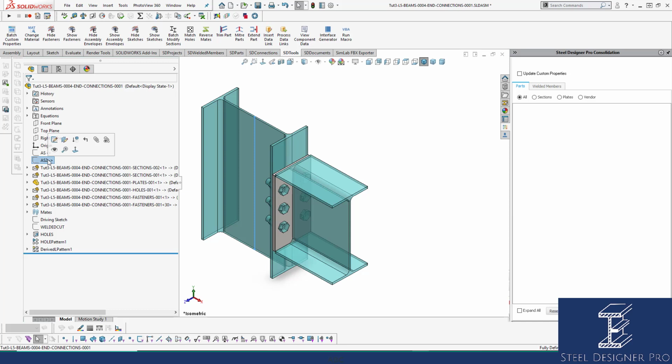and this is where we talked about driving sketches and maintaining a direction, which we keep as a consistent direction of sketching. So when we insert this connection, those attachment sketch segments are related to the driving sketch that holds both the welded members for the column and for the beam, and that locks it in place.